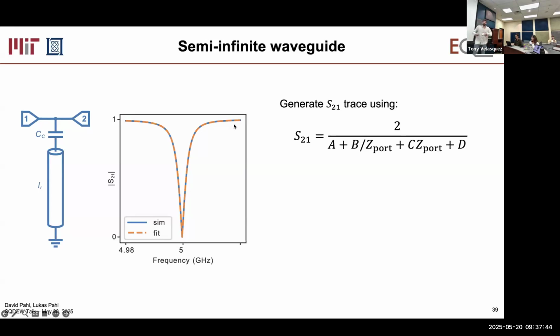That's very different physics than an LC circuit where you have inductance. But you can say that this distributed nature contributes inductive effects that cause something to resonate. If a network was purely capacitive, it would not resonate at all, right? So my most accurate answer is the best way to think about it is the wavelength that fits into this piece of line.